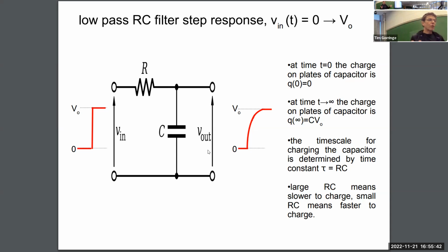So if we wait a long time after changing the voltage on the input, we'll see that voltage on the output. So it's transmitting the low frequency change, but it didn't respond to the very high frequency step of initially applying that voltage on the input. We saw nothing on the output. And so this acts like a low pass filter, a low pass RC filter.